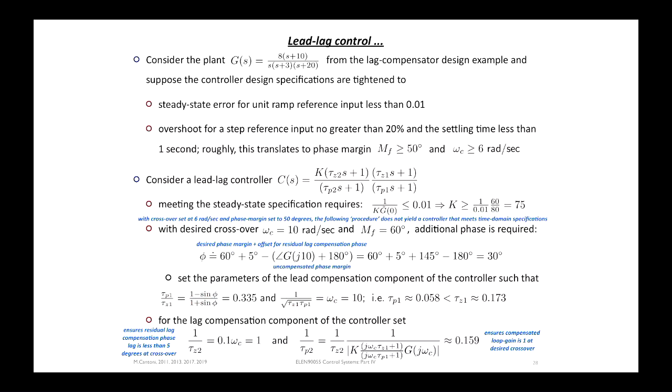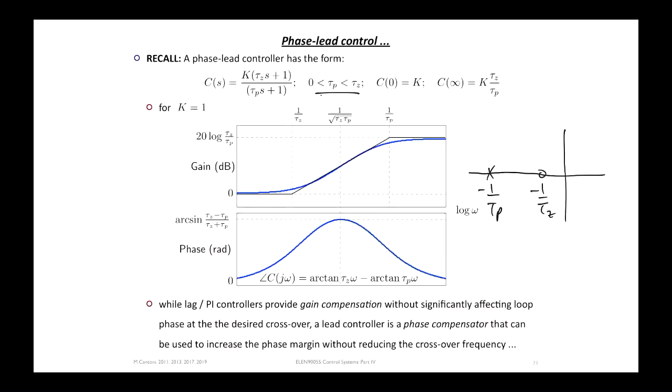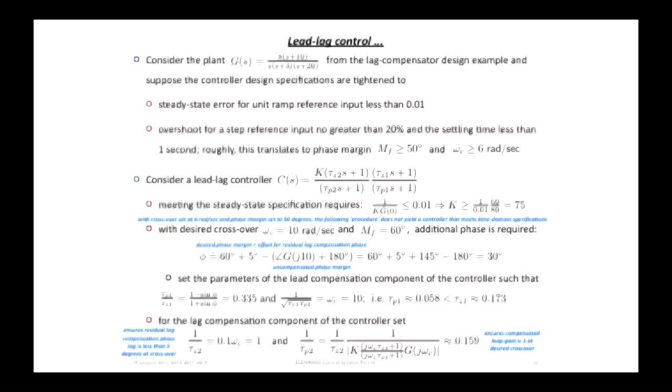Based on lining up the crossover frequency with where you get the maximum amount. So this is just one way of doing things. You can line the crossover frequency wherever you like, right? It's just easy to get an equation that tells you a desired relationship between these parameters by lining it up here, right? But it's not the only way to do it. Right? It's just an example.